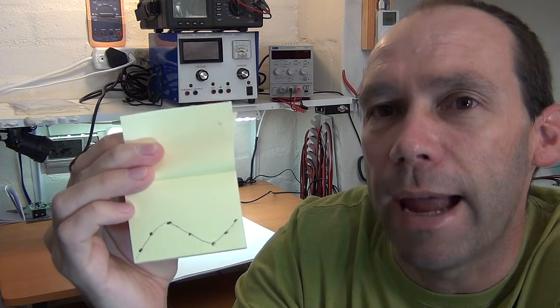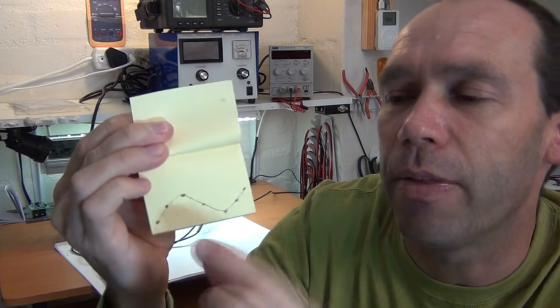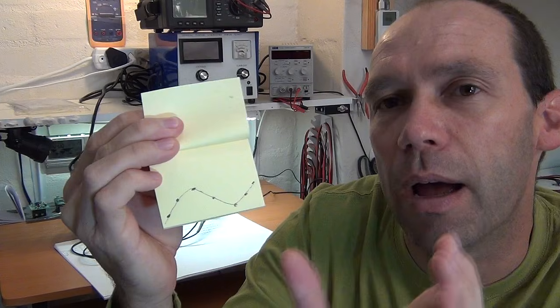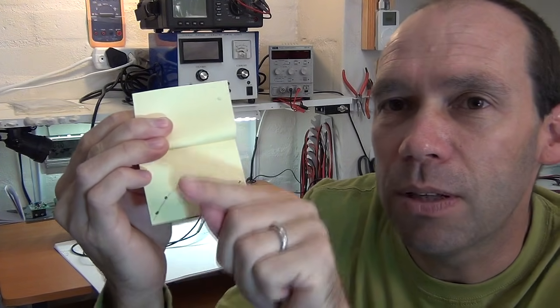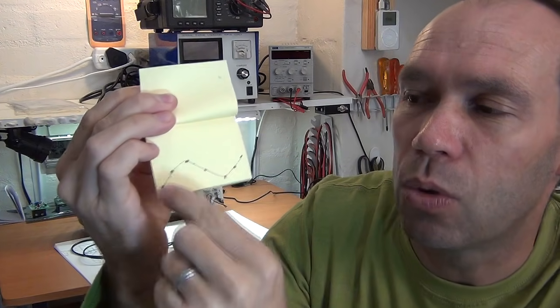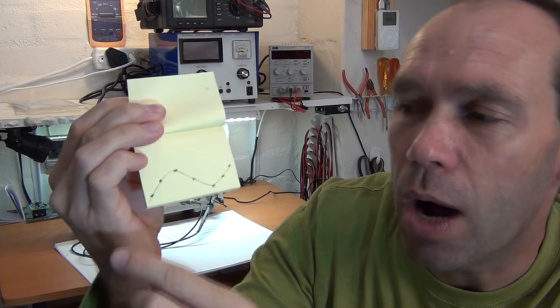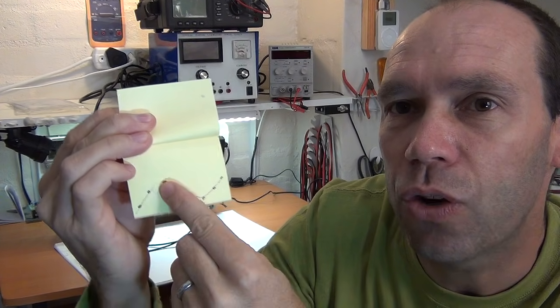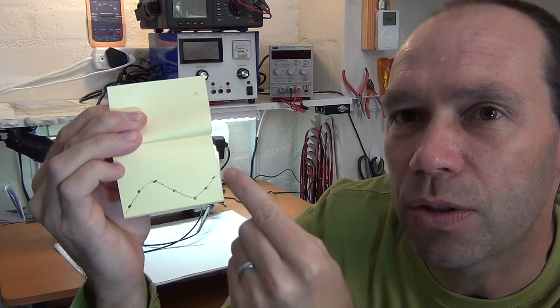And in essence, that's exactly how the old analog oscilloscopes work. They use those old CRT tubes, cathode ray tubes, and it would alter the beam, or the trace as they call it, as it got a signal. And because of your persistence of vision, your eye, it would actually draw a trace and join the dots, or join the individual measurements across the screen. And that's in essence how the original oscilloscopes worked.